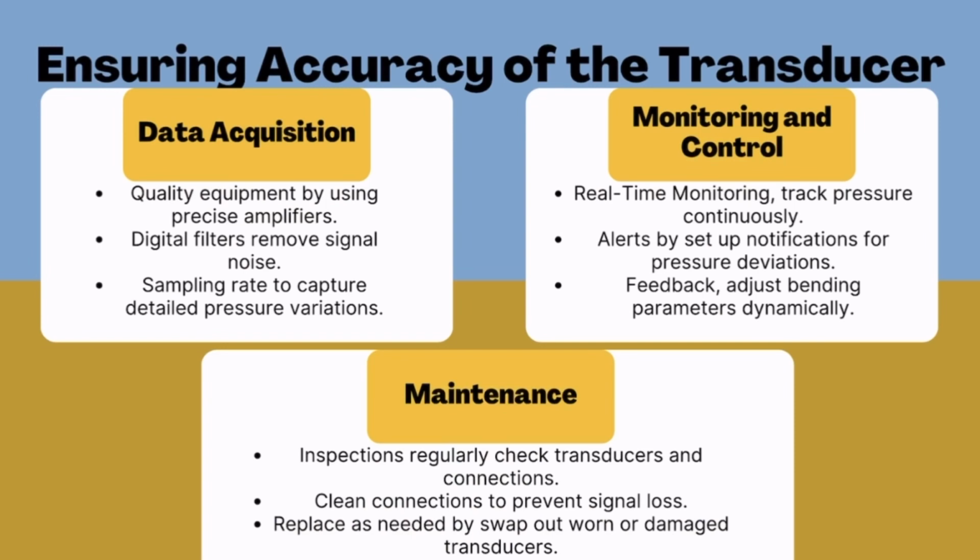Next is data acquisition. Quality equipment: use a precise amplifier. Digital filter: remove the signal noise. Sampling rate: capture detailed pressure variation.